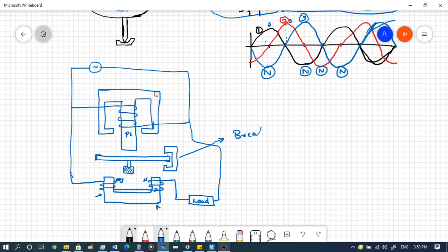It is also known as a braking magnet, because we don't want this disc to continuously rotate because of inertia. Once it starts rotating, it should stop the moment there is no energy being consumed, right? So we need to have a proper braking when the power flow stops.